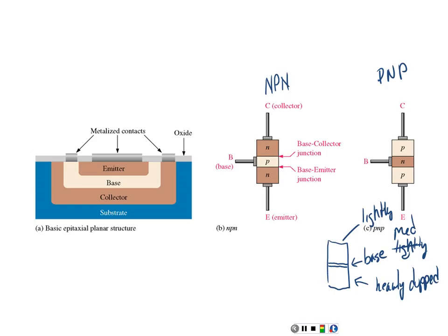Now, when I form those things together, we create ions because that's when they drift across and create that barrier voltage, right? But that's only when we combine these two things. So what you see here is we got two junctions, and that's why it's called bipolar. We have a p-n junction between the collector and the base. So we can check this with an ohm meter.